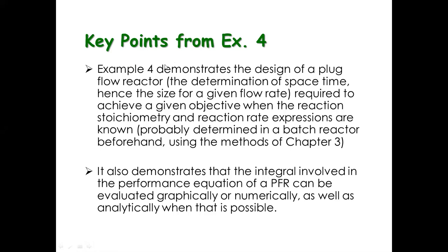In this case, we're not given the volumetric flow rate, but if the problem gave you the volumetric flow rate, the volume will follow because we know that our space-time is the volume divided by the volumetric flow rate. So this is the space-time required to achieve a given objective when the reaction stoichiometry and the reaction rate expressions are known.